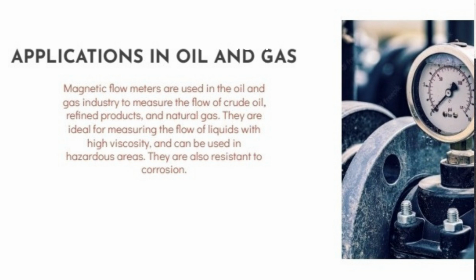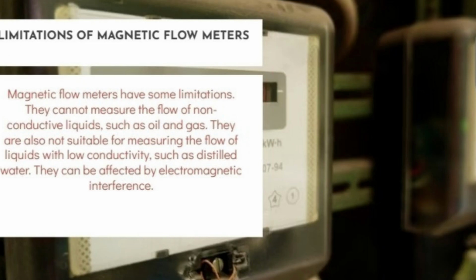And when we discuss the disadvantages of the flow meter, it is relatively expensive and it works only with fluids which are adequate electrical conductors, and it is relatively heavy, especially in larger sizes. It must be full at all times, and must be explosion proof when installed in hazardous electrical areas.